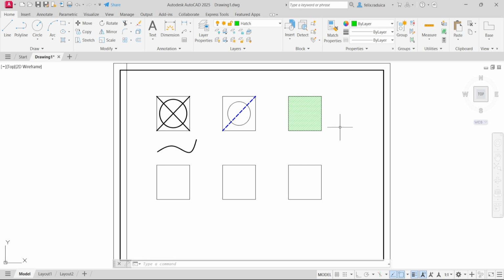So this is what we want. We want to change the scale as much as needed so that we can see the hatch pattern at the zoom level we are at. So I am zoomed out into my A3 format here, and I need to see that this hatch pattern is the way it is because I can distinguish from this what kind of material my part is made out of.